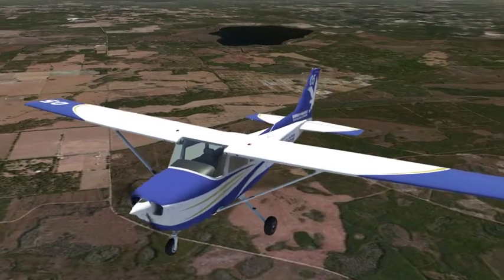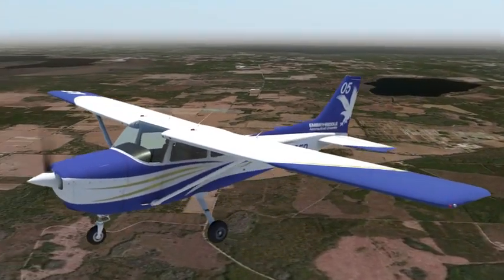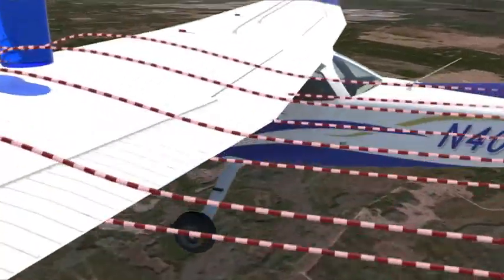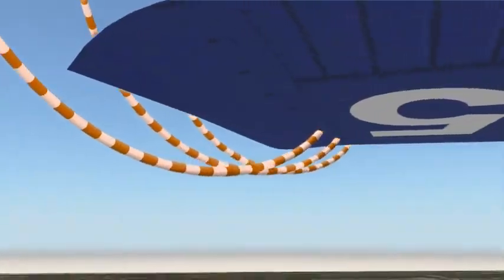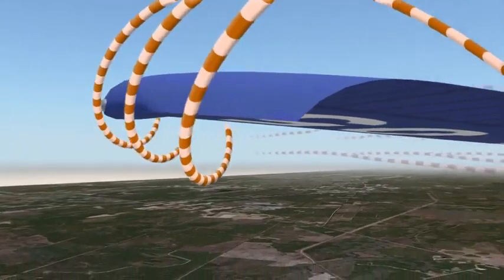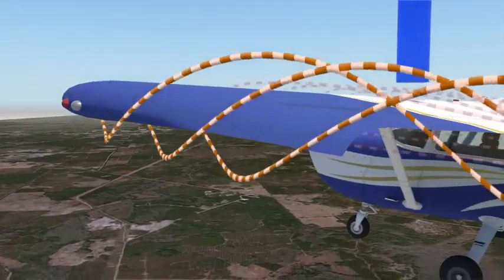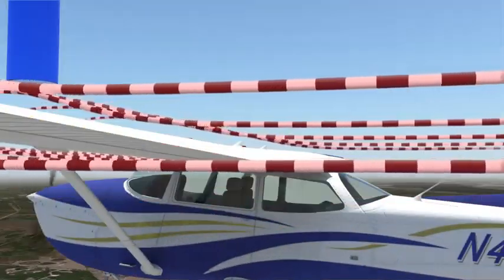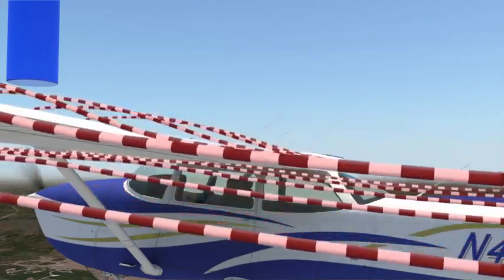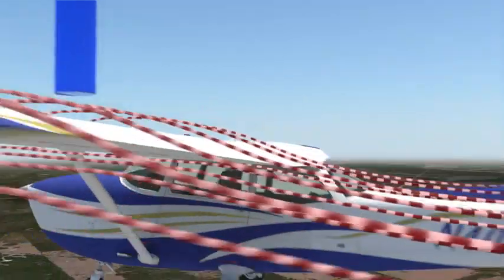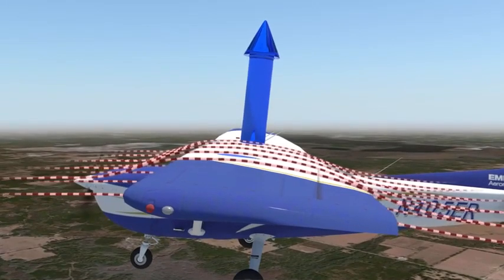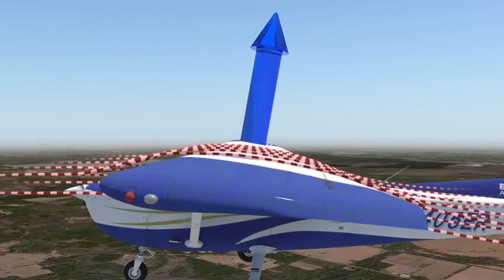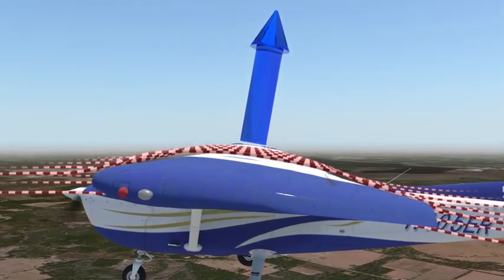The other kind of drag is lift-induced drag, more commonly called induced drag. While the wing is creating lift, behind the wing is a downwash of air. At the same time, the airflow around the wingtips are creating vortices that spiral from below the wing to above the wing. As these vortices wrap around the wing, they actually change the downwash angle of the air flowing over the wing. This, in effect, tilts the direction of the lift created backwards. This shift from completely vertical lift to slightly aft is due to induced drag.